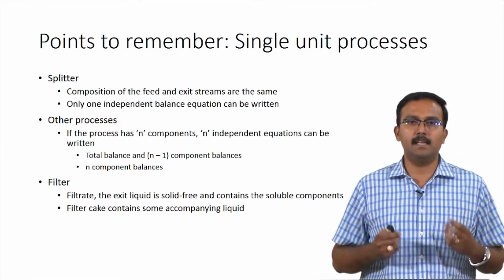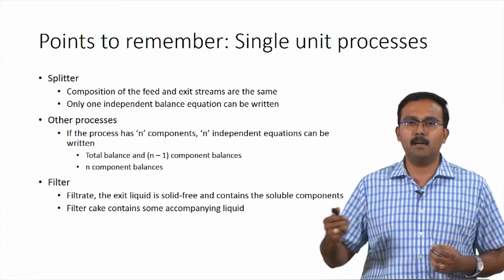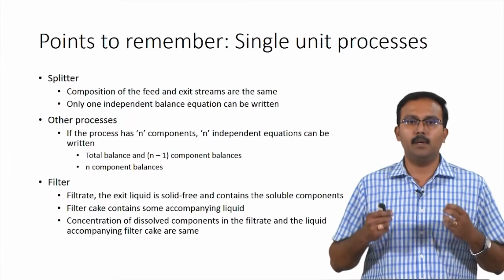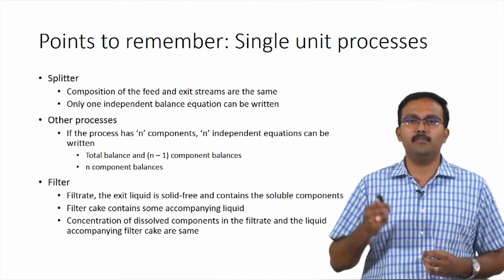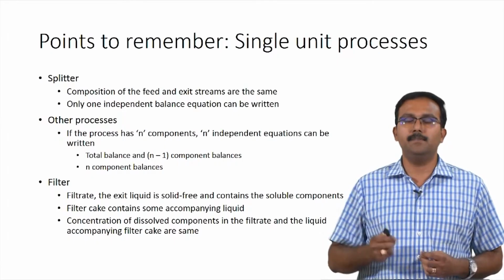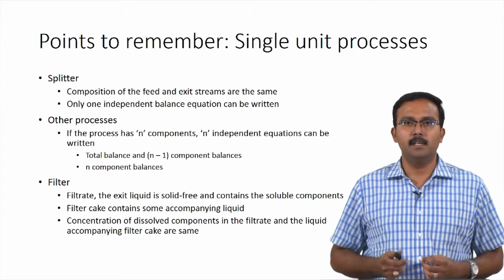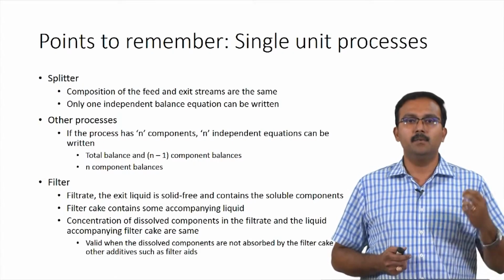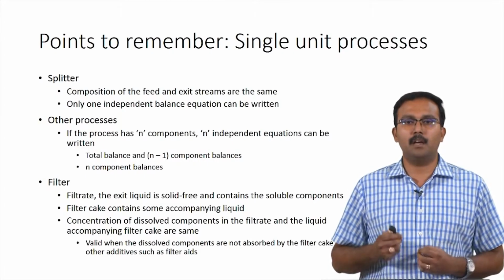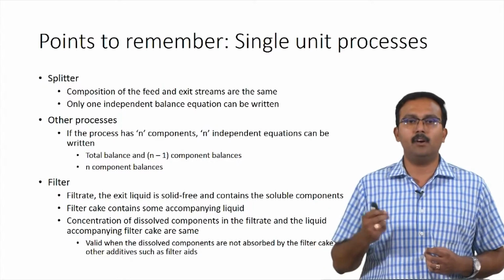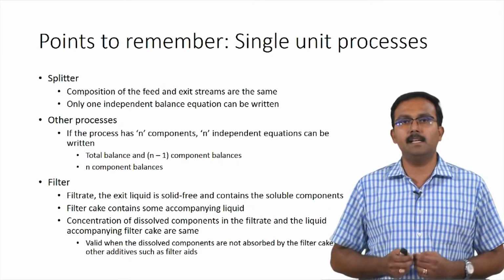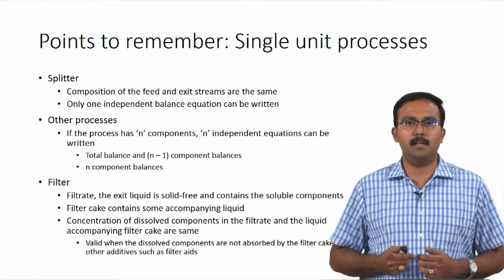The filter cake is the solid which has some accompanying liquid. We need to understand that the concentration of the dissolved components in the filtrate and the liquid accompanying the filter cake are the same. This is valid when the dissolved components are not absorbed by the filter cake or other additives such as filter aids, which may be used during the filtration process.